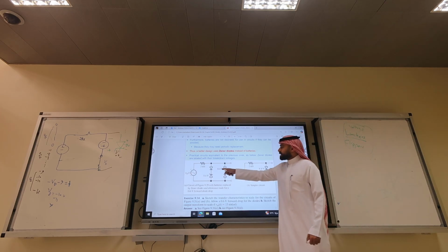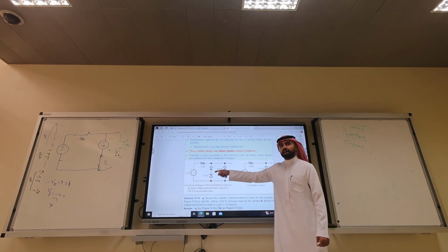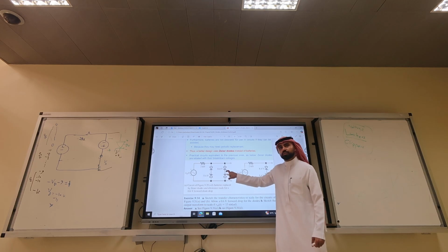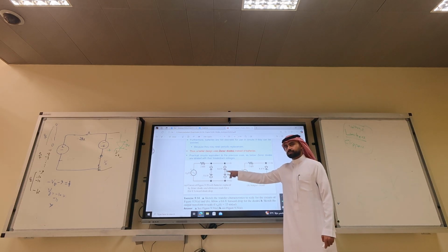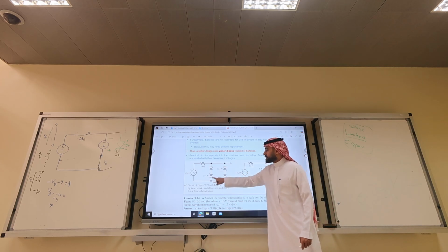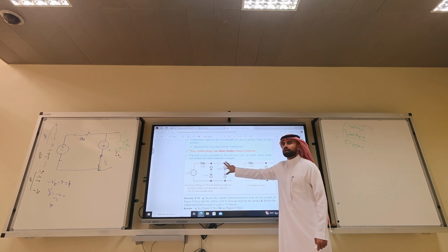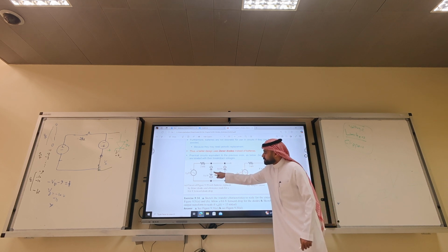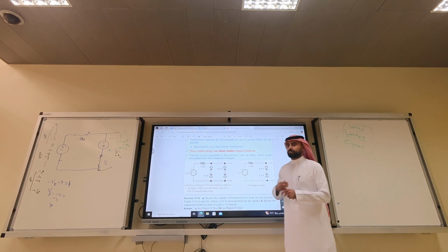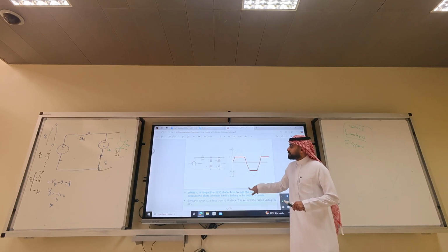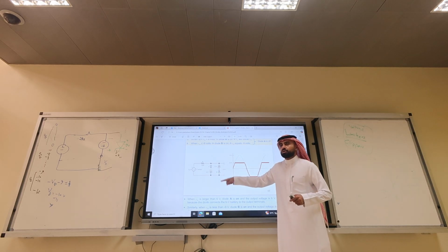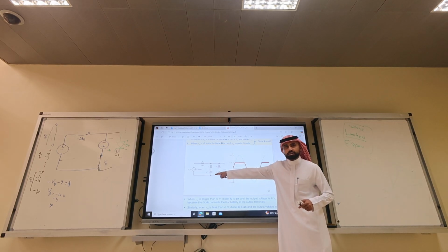Not only that, we added 8.4, which is what? 9 minus 0.6 to include the 0.7 model. Okay? To include the 0.7 model for the original diode. 0.6, 0.6. This is 0.6, this is 0.6. So 0.6 plus 5.4, 6 volts. 0.6 plus 8.4, 9 volts. So this circuit is the one that is practical. This circuit is not realistic. Nobody puts batteries in iPhone chargers.